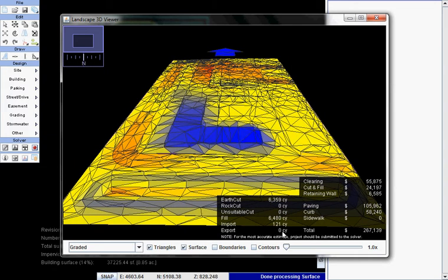And so you can see there are numbers running in the corner here. It's doing an earthwork plan, a cut fill, and we have the properties associated with those values. We have unit costs associated with them. And so it's iterating grading plans for this site, and it's trying to get the lowest site improvement cost here.